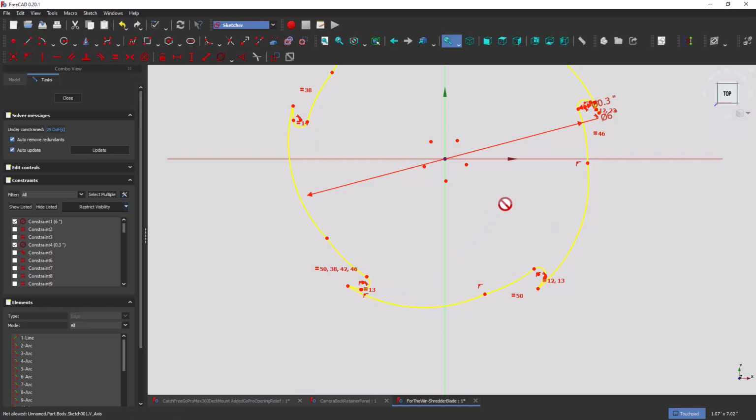Now, if everything works, our vertices are all tied in together. And this looks pretty much like the outline of the blade. Now you play with the geometries. You can make the circles a little bit bigger to make your teeth larger. You can change the length of the flat spot that goes out to the tip to make that right. But this is basically it.